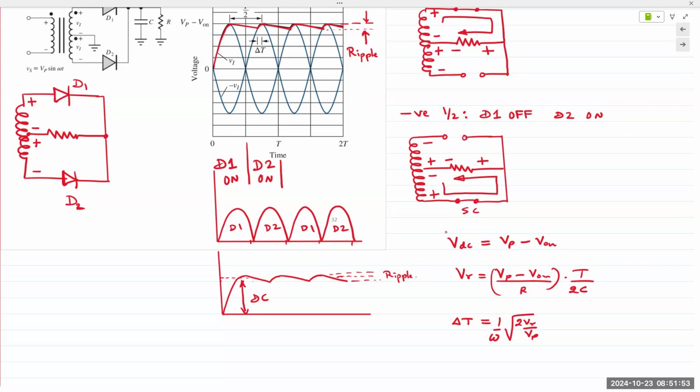So if we wish to compare and summarize, we can find the capacitor value depending on what kind of ripple voltage we desire. Now, obviously, as I stated, in real life, an entire DC power supply is much more complicated. We have a lot more components in there, one of them being a Zener diode. The Zener diode can hold the voltage constant when it's working in reverse bias.